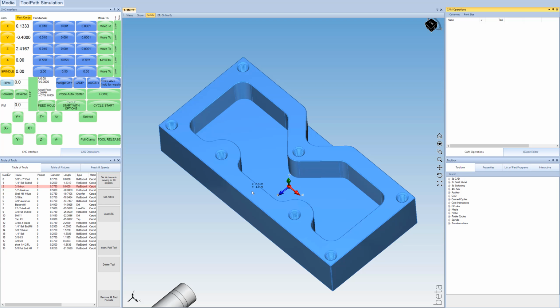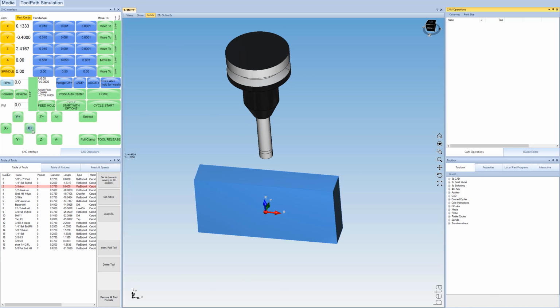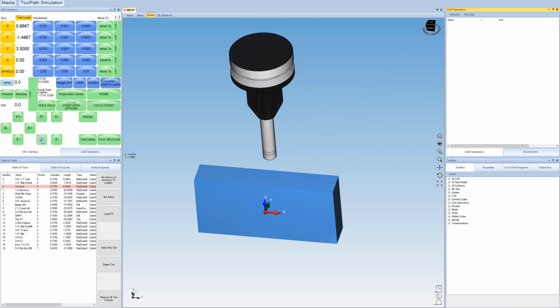machine. So conventionally you would program on a system kind of like this, on an offline computer, and then you would post-process your G codes and put them on the machine. With this system, we bypass all of that. If we were actually connected to a machine right now, I would press the X, I could actually jog the machine around. The machine would actually be moving right now.